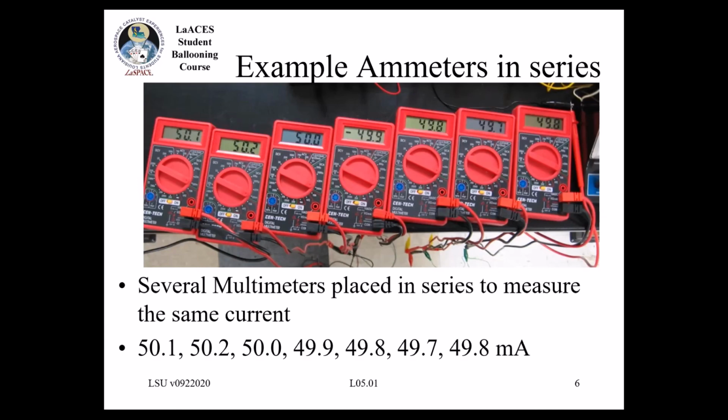And if you're wondering about the negative in the middle there, that just means that the probes for the multimeter were flipped. So current was flowing in the black terminal and coming out of the red terminal. If you switch those leads around, that would just become positive.